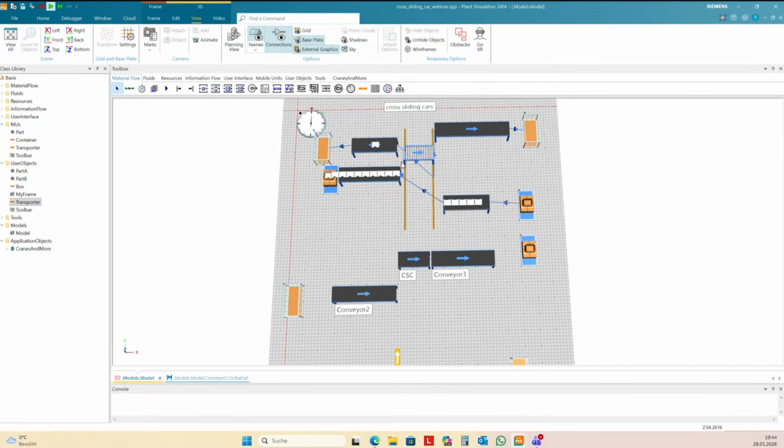And one problem you have is if you need to change the direction after transporting the part. The base here is a conveyor, and on the conveyor you cannot change the conveying direction, so you need a point-oriented element here that you can change the orientation of, or you need to turn completely, for instance like in my second example.